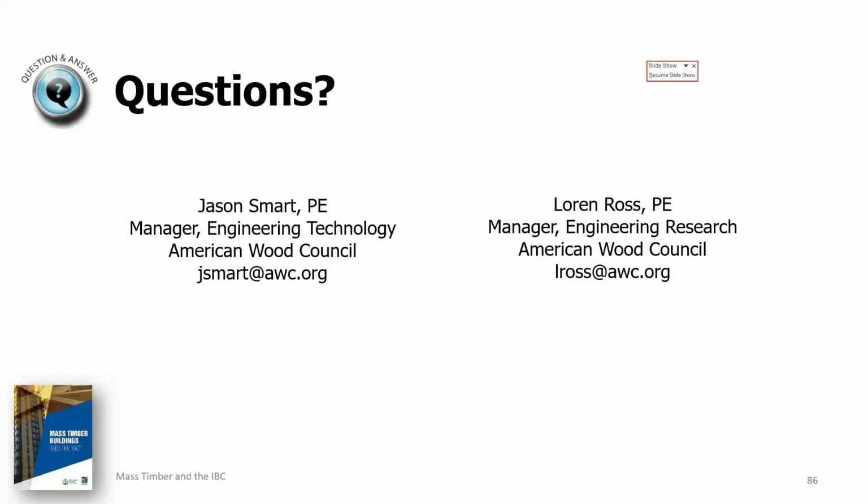But there's no prescribed time assigned to any fire resistant or intumescent fire caulk, because of course those are proprietary formulations, and performance varies from manufacturer to manufacturer and from product to product.